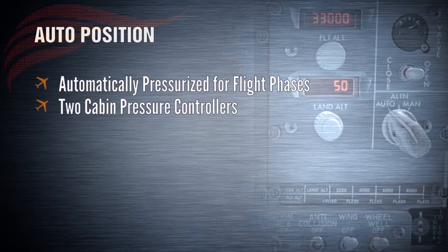To provide system redundancy, the automatic control system has 2 CPCs, but only one of them works to pressurize while the other is on standby. With each new flight, the pressurization system switches the active CPC in order to maintain an equal amount of wear and tear between both.